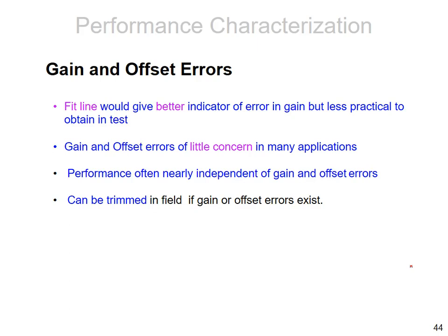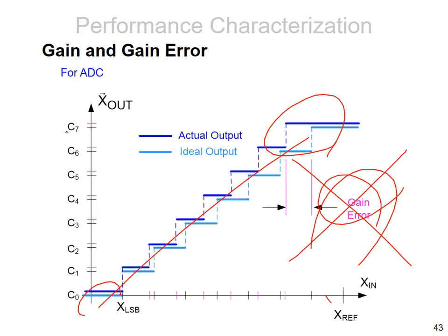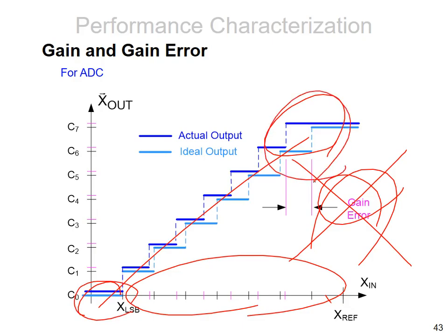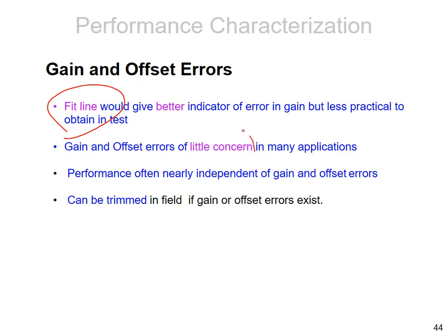Never mind the gain or offset errors. If you would like to get a better value through the help of a fit, you can take all the breakpoints into consideration to decide how much offset error here, how much gain error over there. But anyway, they are not important at all, I mean, for usual applications. They are only important for references.